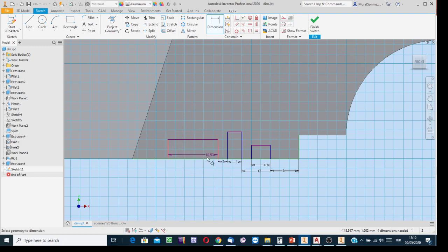And this one is in the size of, let's say, 4 millimeters. Height of the channels, from here to there, you see the projected line is the reference to input the constraints. This is equal to, let's say, 3 millimeters. The height of this one is from the same reference, let's say 6 millimeters. So on and so forth. This is in the size of 5 millimeters, etc.